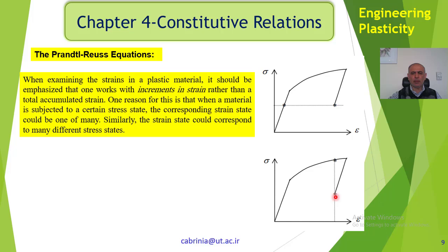That's what I mean here, and that's why we are going to have these constitutive relations for plastic materials or the plastic behavior of the materials. We use the increments of strain rather than the total accumulated strain. That's one reason for it.